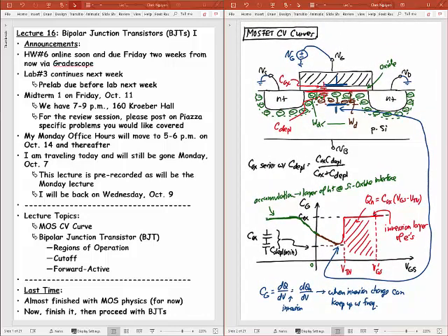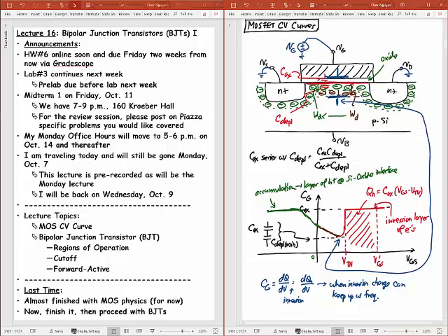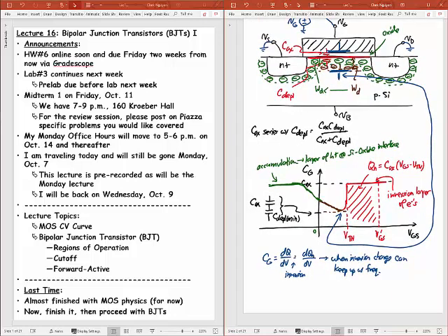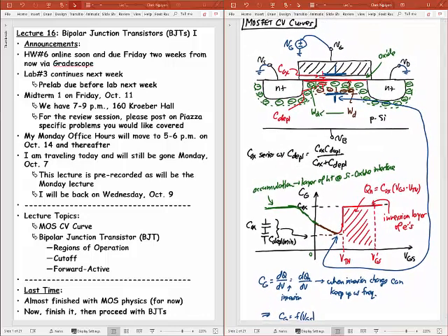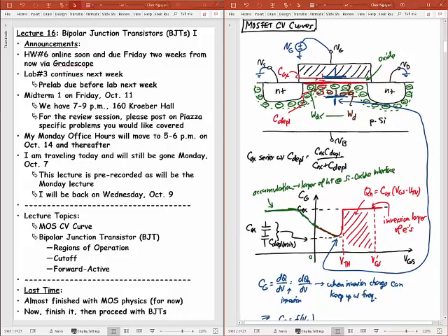So all this that I'm showing you here is really just to say that the main point I'm trying to make is that the capacitance of my gate, seen across the gate, is going to be a function of the gate voltage. Okay, which means that it is now one of these nonlinear, more generalized capacitances that we've been talking about. So just another aspect of the MOS device that you ought to know at this point, and that you would learn a lot more in EE130. But at least for now, you've got a little bit of an introduction to this.